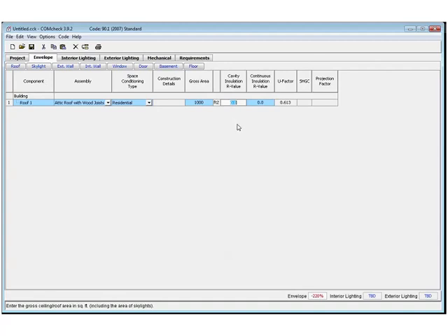So if this insulation is being installed at the ceiling plane, and it's all one application, blown in, or it's batt, whatever it might be, it's going to be across structural members, right? It's going to be between the wood joist truss. So you enter your value as all one. Only would you enter continuous insulation here is if you had insulation foam board that you are using, and of course with this one I don't think it would apply.